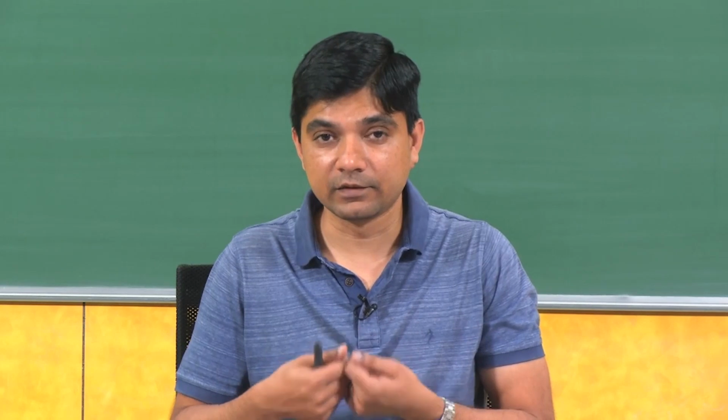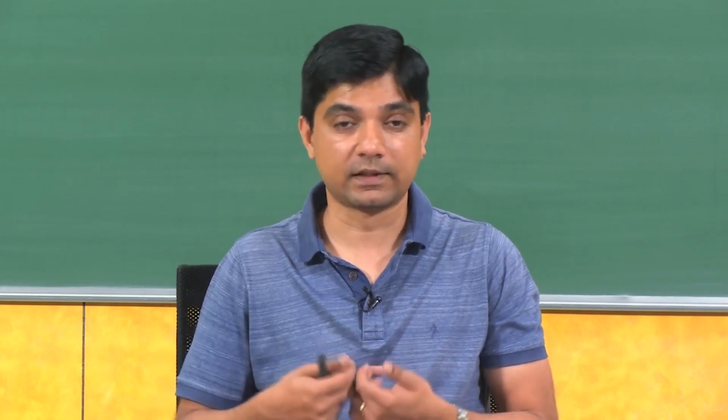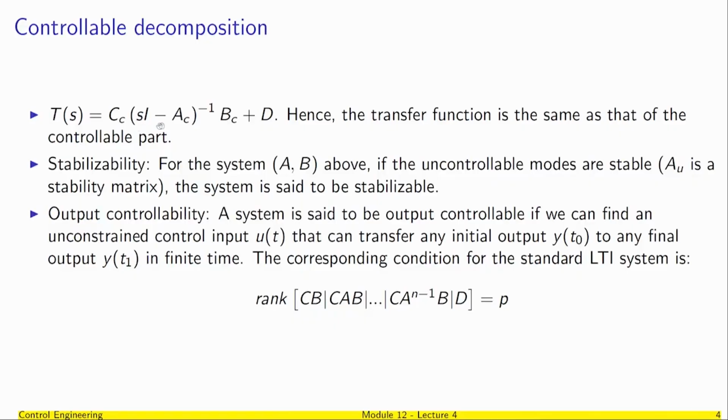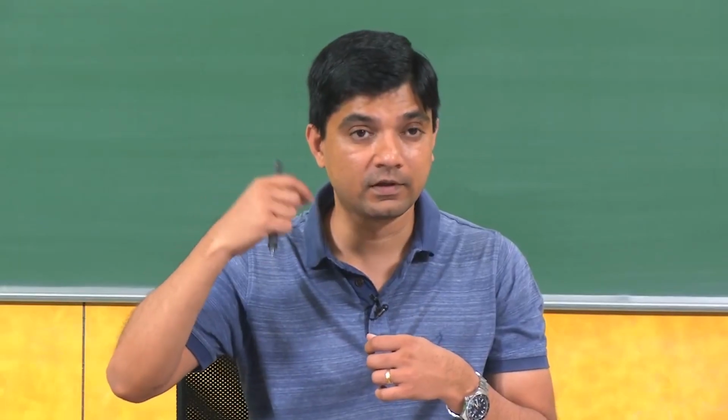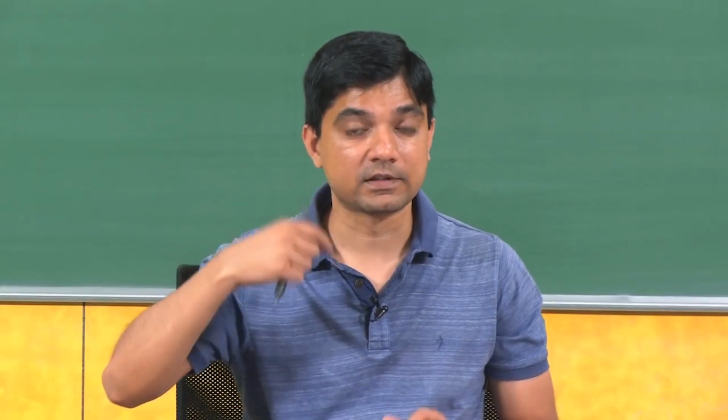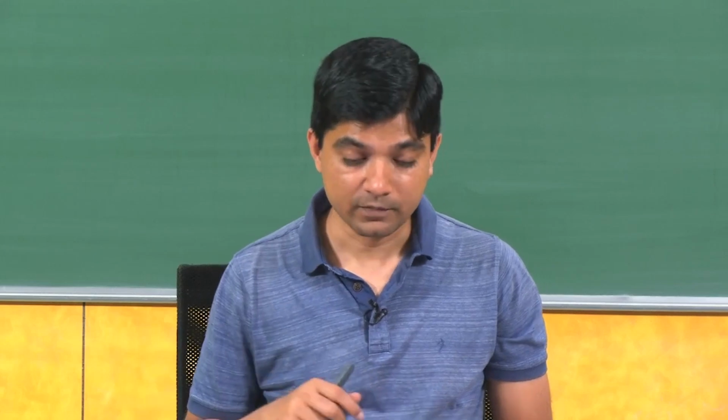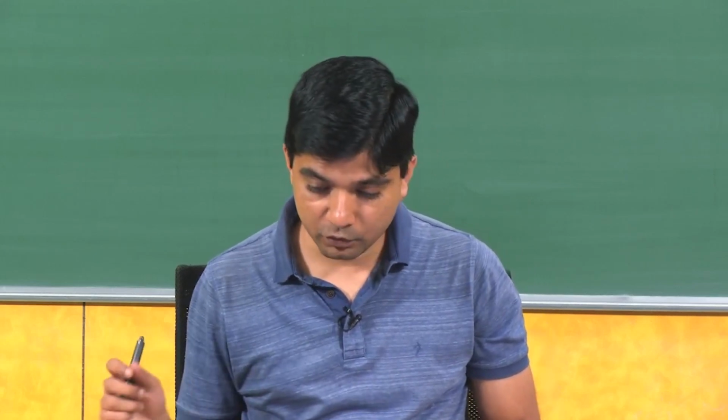Therefore, whenever I give you any transfer function, I could do anything with that transfer function if and only if I know that this is a transfer function of a completely controllable system. Otherwise, you see that some poles of the system go missing, or there is some kind of inherent pole-zero cancellation whenever the system is not completely controllable. So, what can we do with this kind of systems?